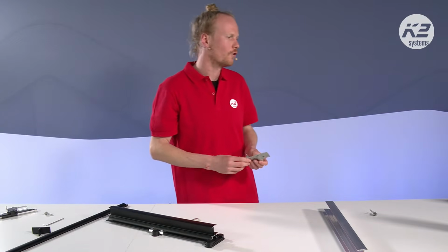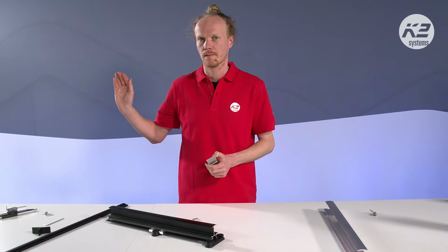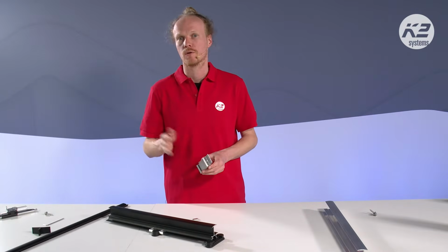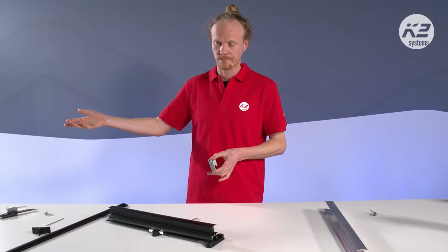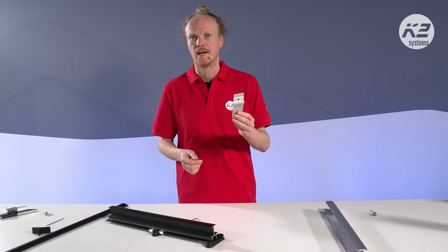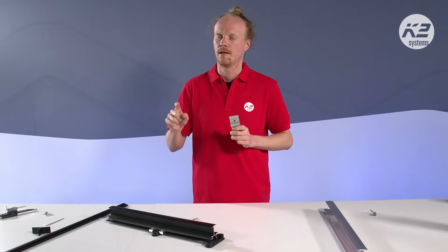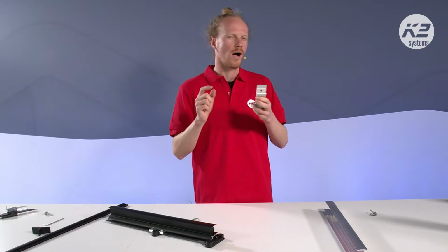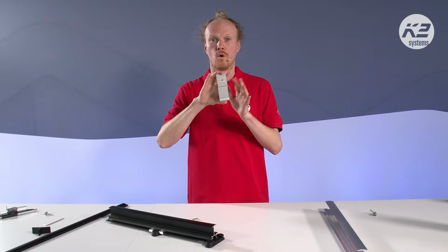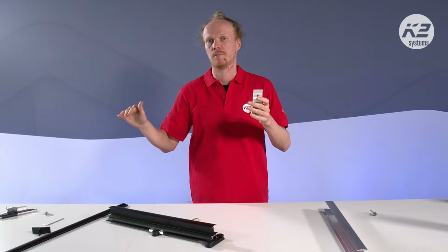For our other systems, our facade systems, all of our other pitch roof systems and the multi-rail, which the question and Vlado spoke about before, you would first have to screw in the multi-rails in the same way we've done the basic clips. Then you would have to place the cross connectors in. The cross connector installation with the basic rail is a little more difficult than the installation with the basic clip, because you actually have to align all of these first. You put in, let's say, 10 of them, and then you put the rail in, and these all have to be perfectly in line.